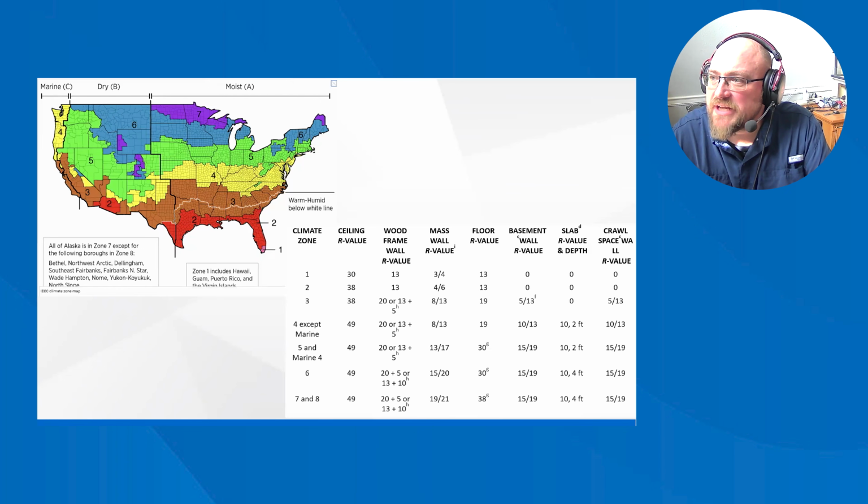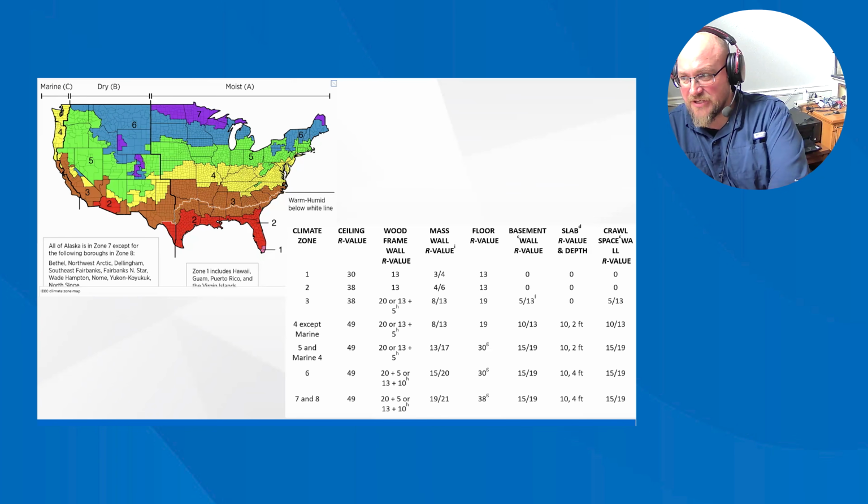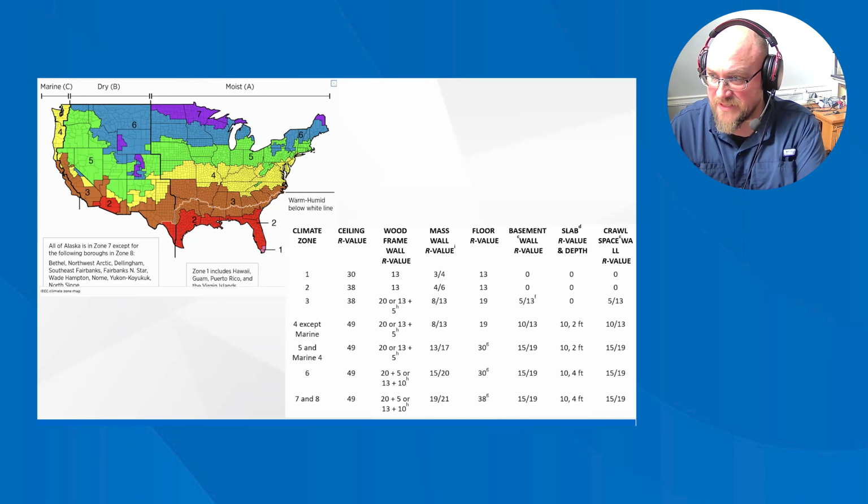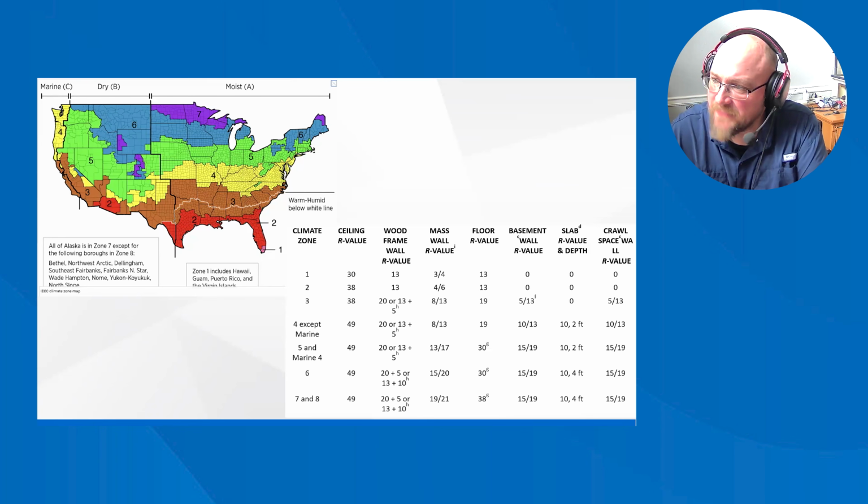The insulation recommendations for ceilings, wood frame walls, floors, foundation walls, crawl space walls, and slabs have been increased overall and generally exceed those required by most building codes. The Department of Energy's range of recommendations is based on comparing future energy savings to the current cost of installing insulation. You can use the map and the tables in this section for new and existing homes as a reference guide for your inspection and evaluation of their insulation.